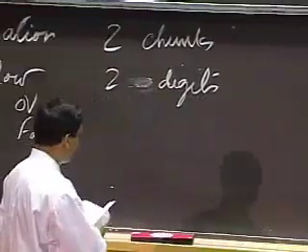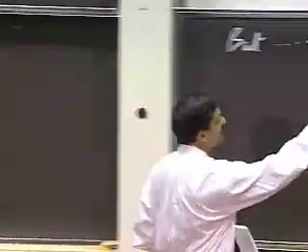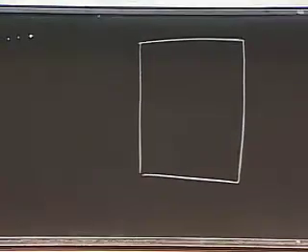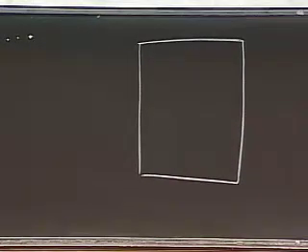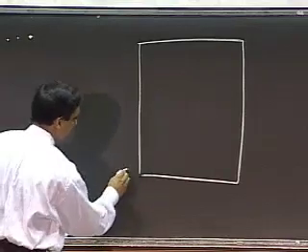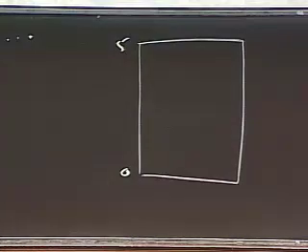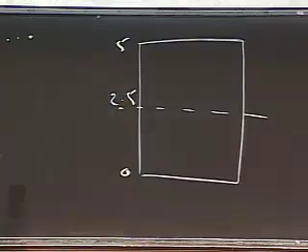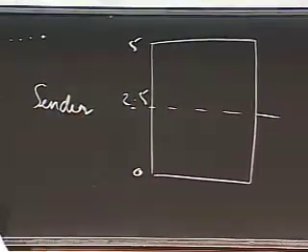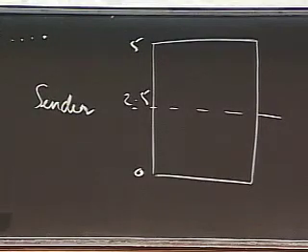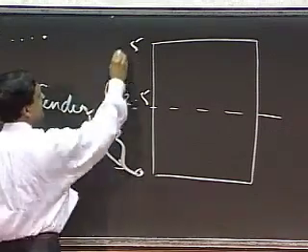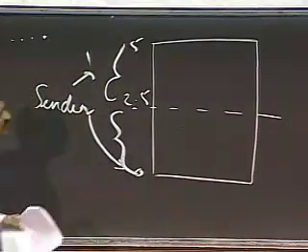If you look at that signal there, what I ended up doing was creating a design space that looked like this. This is on page 6. I said the range of values is 0 to 5. At 2.5, I drew a line, and I said, as a sender, if you wanted to send a 0, you would send a value here, and if you want to send a 1, you would send a value here. Similarly, for a receiver,